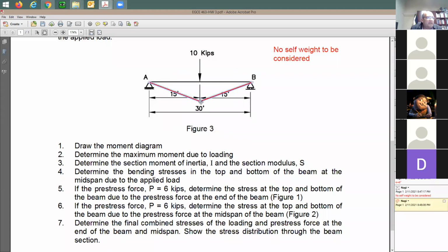Just imagine you have a cable, right? Here's a cable. You start to put the point load. What's going to happen to it? It's going to come down. Later on, I may show you very simple ways of doing the moment diagram just by feeling, and do it on the tension side. So where's the tension side? It's going to be here. So you put the moment on the tension side of the beam. If you'd like to do good design in concrete, this is the way you do it.